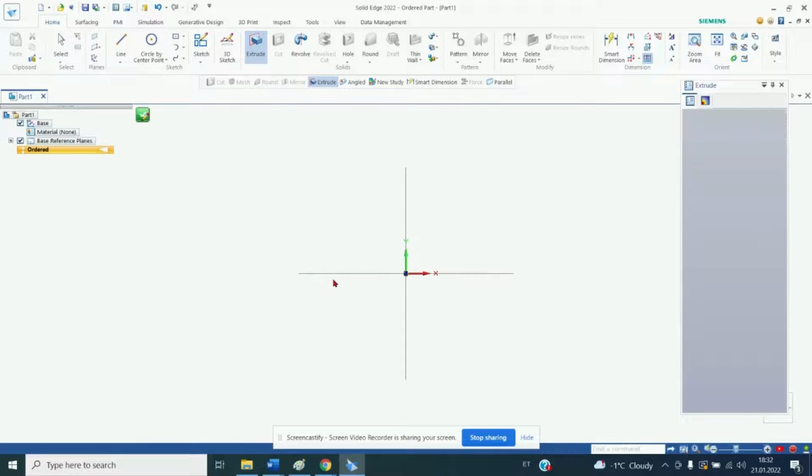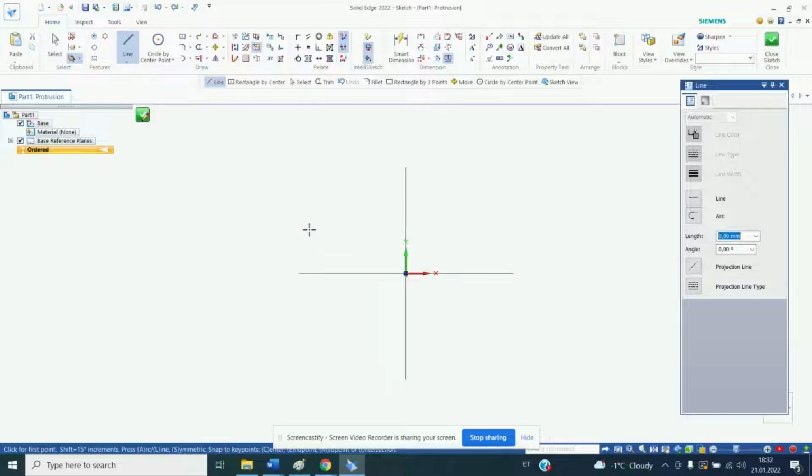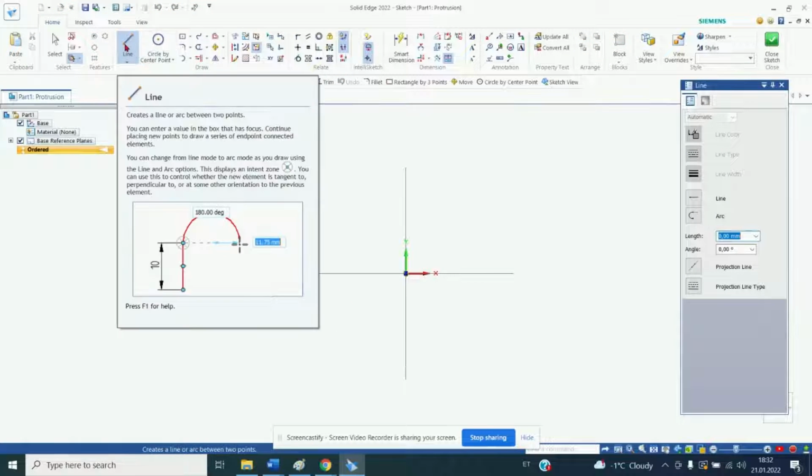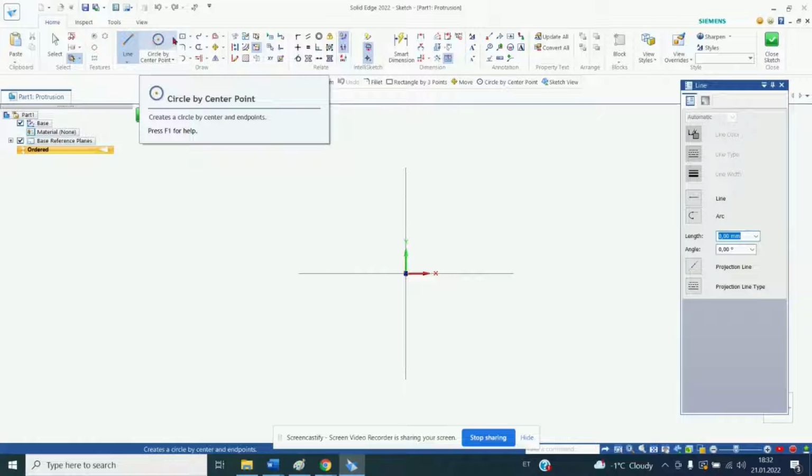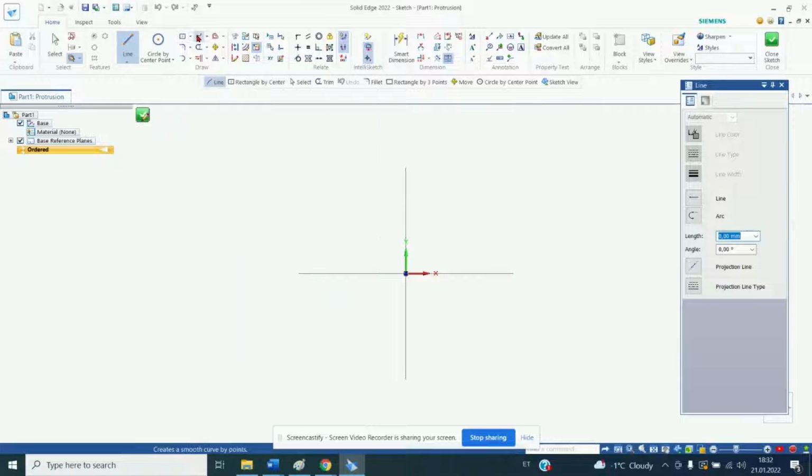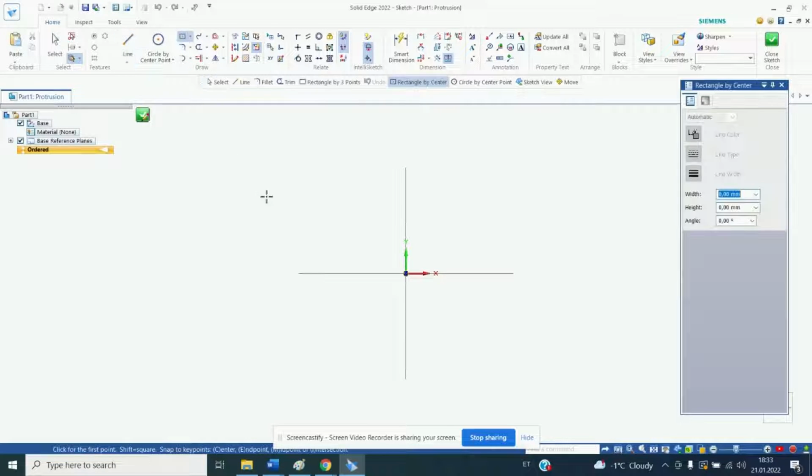In extrude mode, you can use draw tools to make your model. In this video we look at basic commands: line, rectangle, circle, curve and cut. Now let's start drawing. Select rectangle and make a 90 x 110 mm rectangle. You can draw by hand or you can type values and press enter.